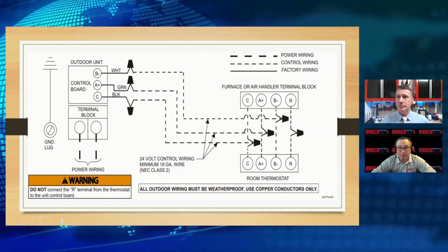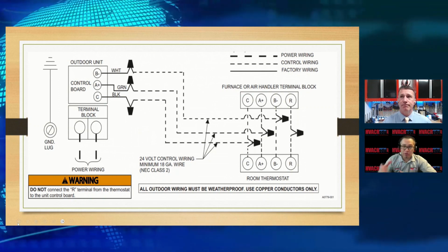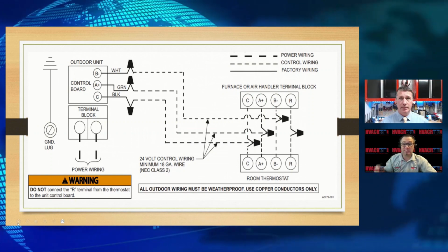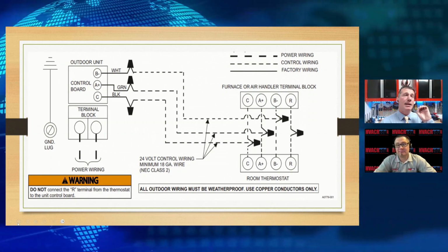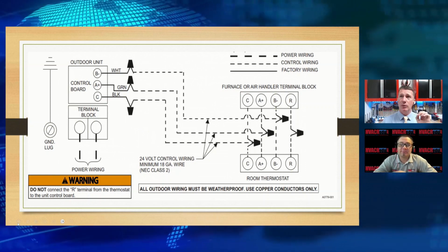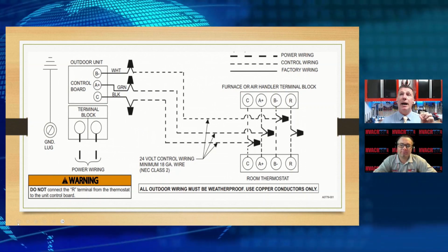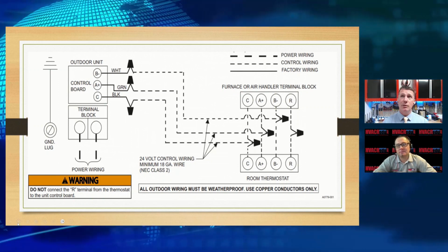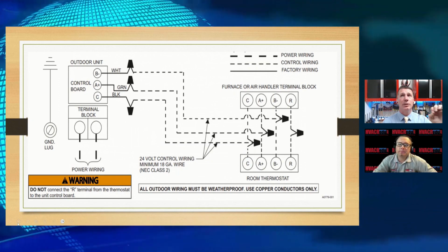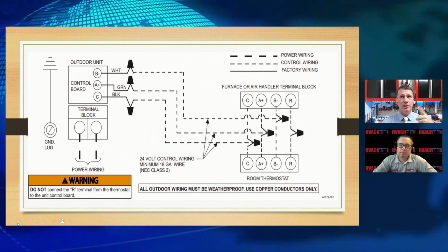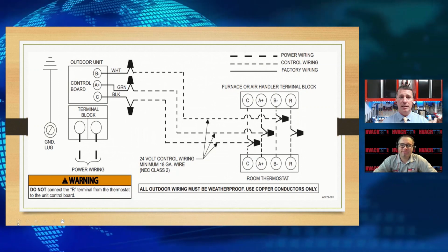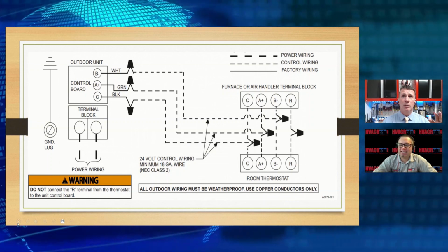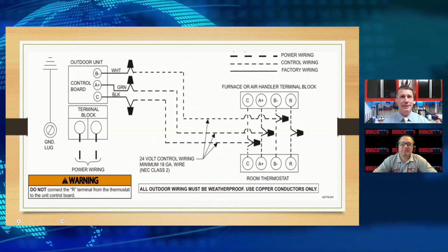Yeah, pretty much. It's just a different protocol, a different language, but it's being delivered to one controller or the unitary devices in the same way. Now, I will say that I cannot speak for the bias voltage between 1 and 2 for the rest of the manufacturers. I know Climate Talk pretty well, and there's a lot of training material for that. If there's anyone out there that has tested the bias voltages and knows more about them between different manufacturers, I'd love for you to hop on, because that's a piece not every manufacturer likes you to disclose. So I'm curious myself, but I've got my own ideas.